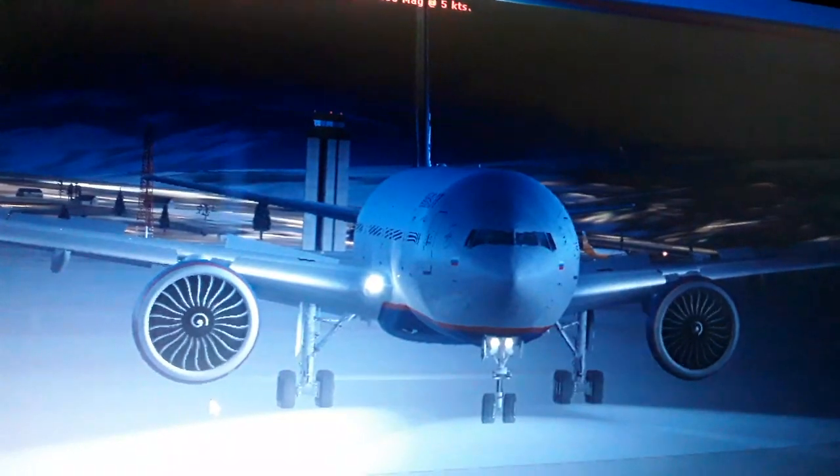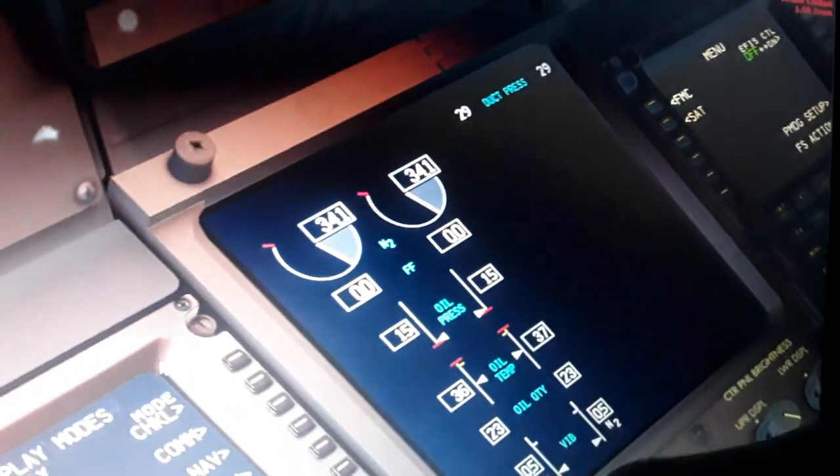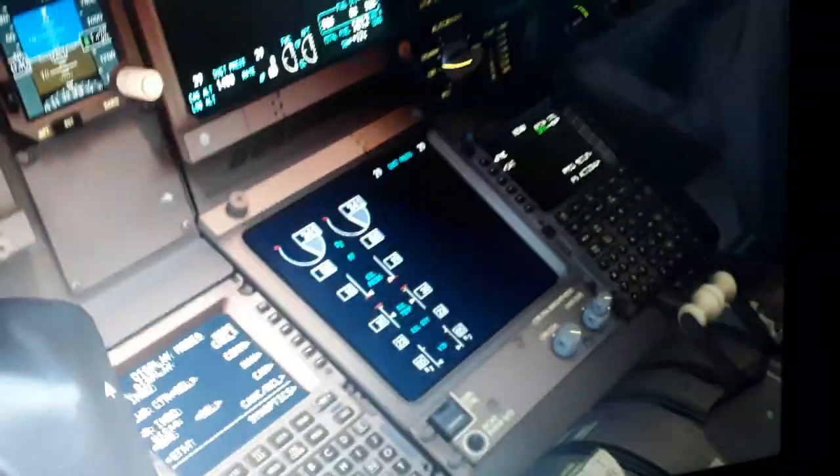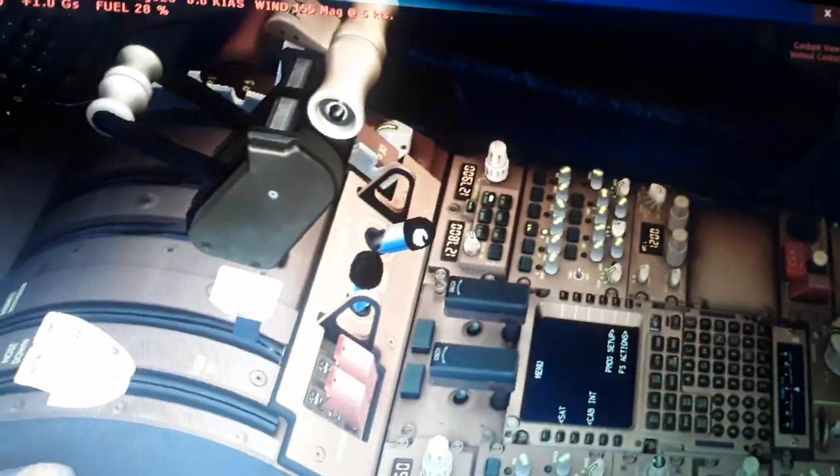As you can see, the left and the right turbofan is still slow because there is no fuel flow. It's only the pressurized air from the APU inside the engine. So you come here, you can see there is no fuel flow. So we start the fuel flow like this. The fuel control left and the right engine on.